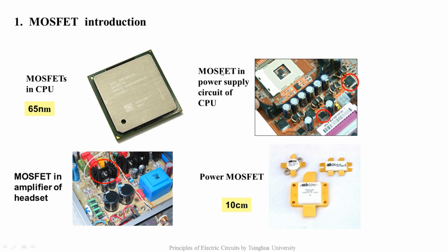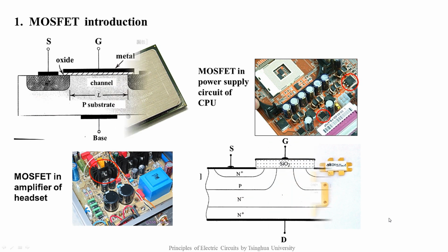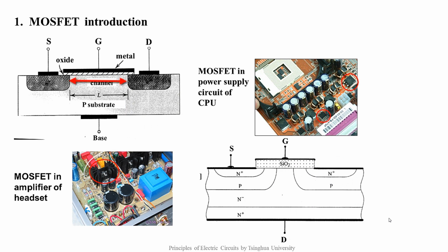Thirdly, the internal structure of these MOSFETs also have differences. MOSFETs applied in the low power cases have horizontal conduction channel between D and S, while the power MOSFETs applied in the power system have vertical conduction channel between D and S, which can raise their voltage level.